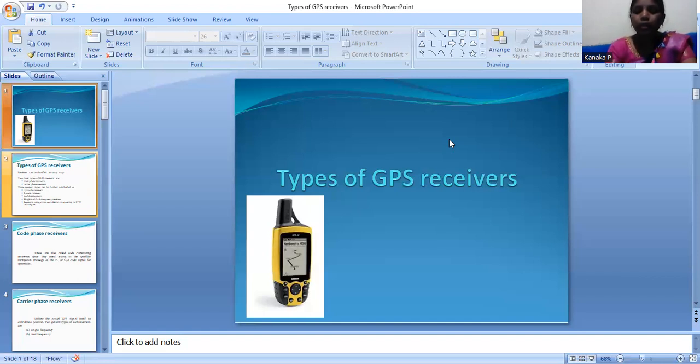The master control station is responsible for overall monitoring and transmission. The second one is monitor stations, which make pseudo range and delta range measurements. Each monitor station checks the exact altitude, position, speed, and overall health of the orbiting satellites, all to be covered by the monitoring station.